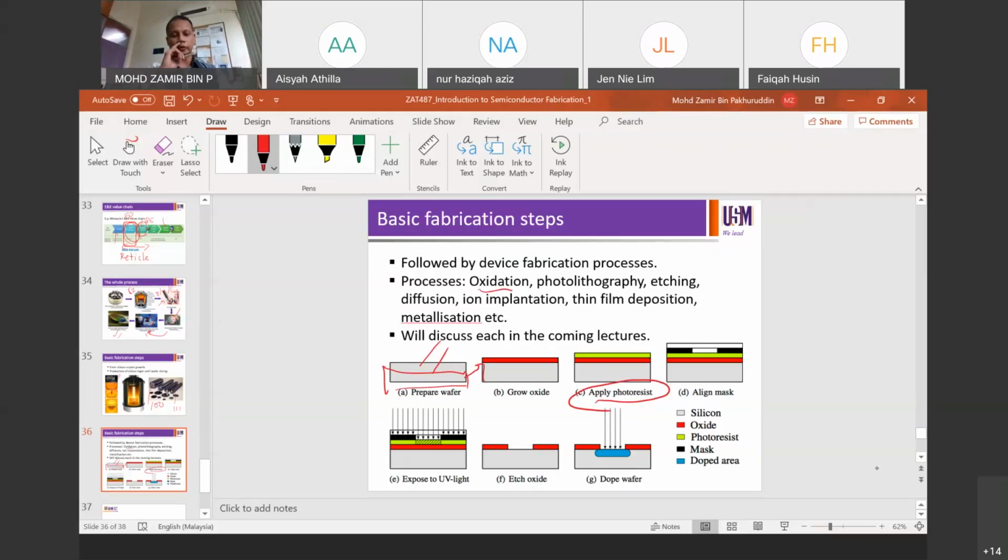Photoresist in the lithography process is a light sensitive polymer. That means it can react based on the wavelength of the light. That's one of the reasons why the lithography space has to be yellow in color, to avoid contact with visible light that will induce some other mechanism in the photoresist. We're going to learn that later on.